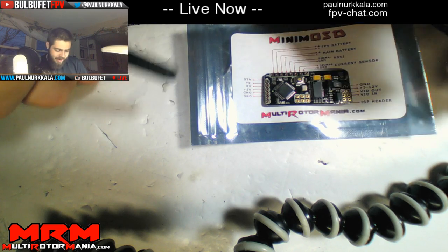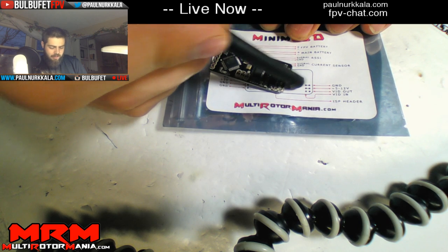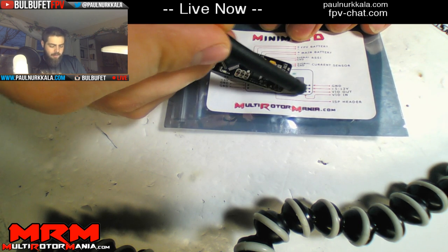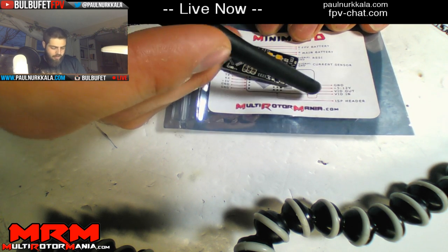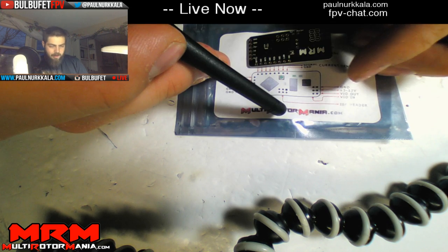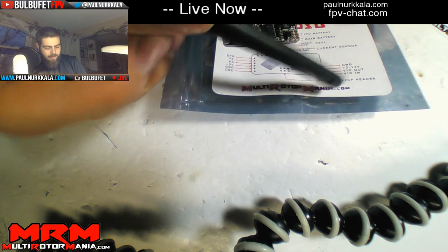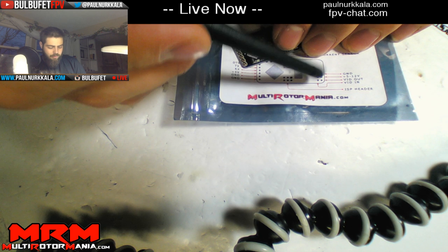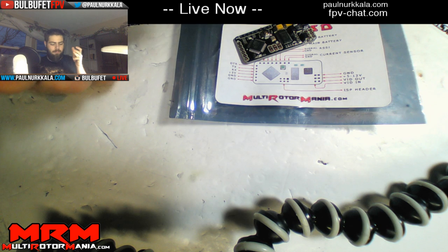And then finally on this side, you have a ground. You have plus and minus 5 volts, and 5 volts only. For some reason it doesn't quite work on the 12 volt. But I'm going to plug it up to the power distribution board anyway, so we'll talk about it more. And then finally, you also have video in and out for the OSD to be put onto the video feed.